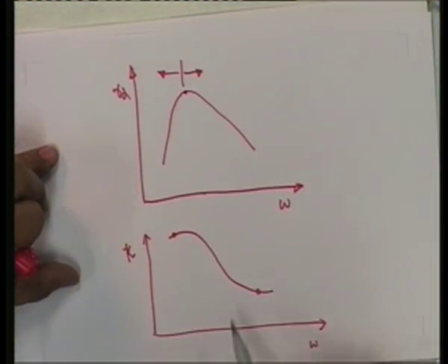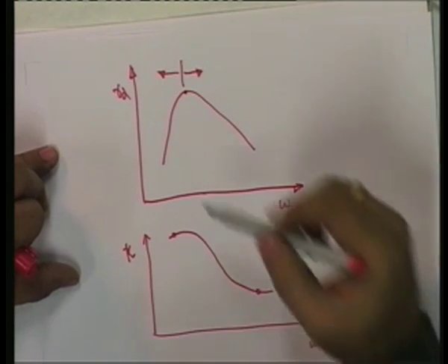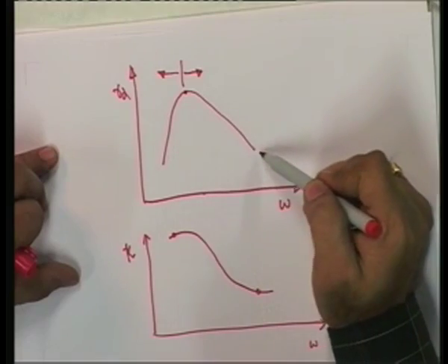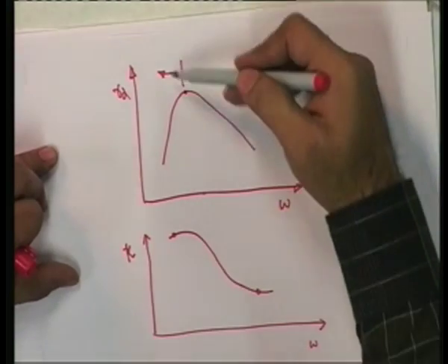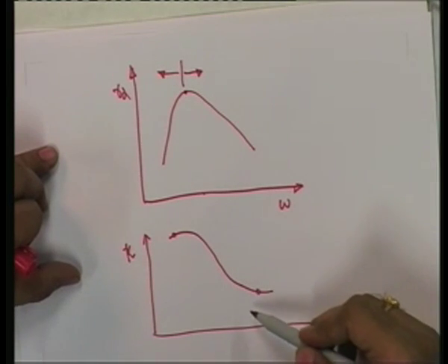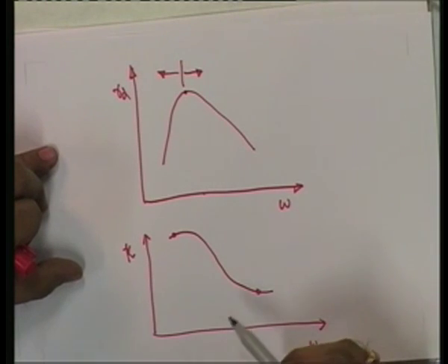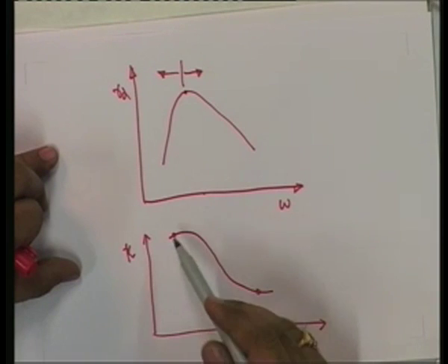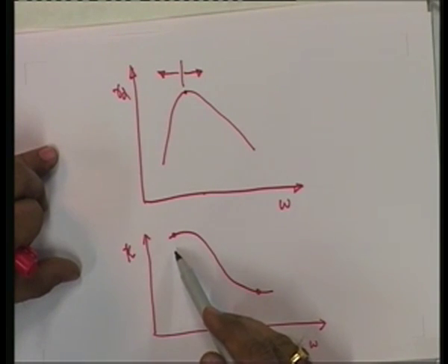So, what is happening is that as we increase the water content, for example in the compaction process, the orientation of the particles changes, that is, the structure is gradually transforming from flocculent to a dispersed structure. As we increase the compactive effort, this also shows that on the dry side of optimum the permeability value will also be less with an increase in the compactive effort.